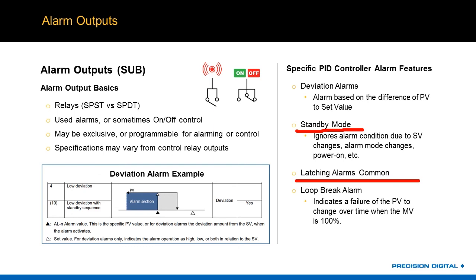There are special FM limit controllers, if any of you are familiar with those, and obviously for that you need an FM approval, which most PID controllers, including the SuperNova, will not have because they're PID controllers and not limit controllers. But if you don't need that FM limit controller, most PID controllers can do that limit control function.